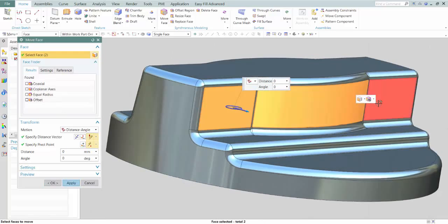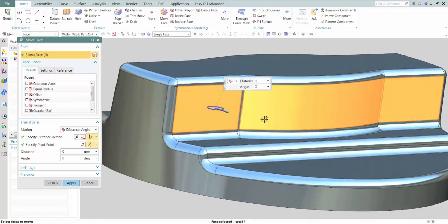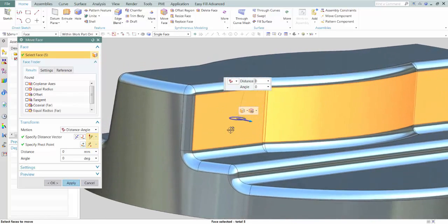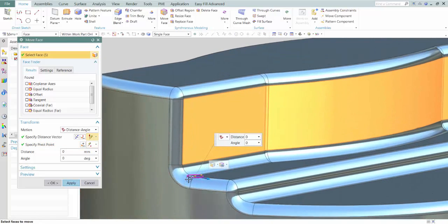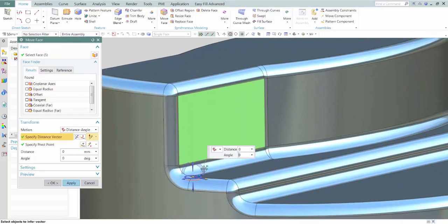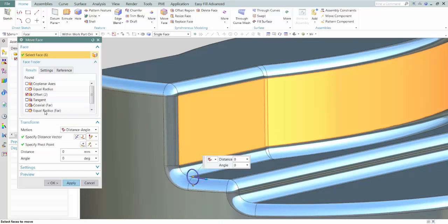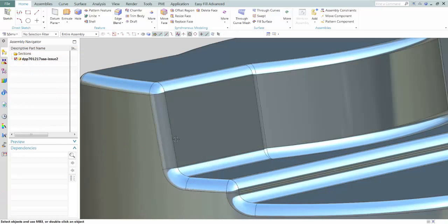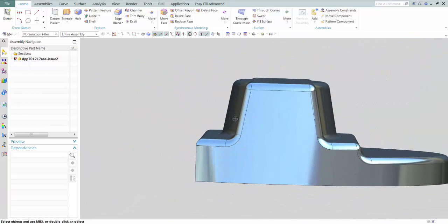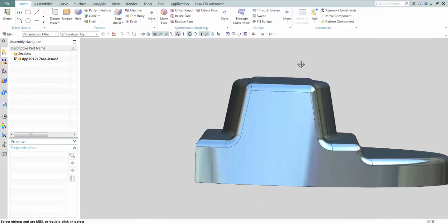Now I'm going to do that exact same command again so you have a little bit of an idea of where I'm going with this time. I'm going to grab all those faces. I'm just going to place this. This is just a little control component we use out here to orient things so we can give this a proper direction. And I'm just going to tell it, again, maybe I just want to put, and we're over exaggerating it here just a little bit, 10 degrees of draft angle on these faces, but it's so you can easily see how we've put those angles on there.